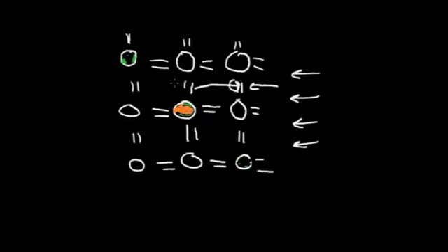It has an extra electron that's just sitting there. Now if we apply an E field, this electron can move. So if we add more phosphorus atoms, we add another electron that's free to move around. So we can change the conductivity. We can make this, instead of an insulator, a conductor by adding more phosphorus atoms.